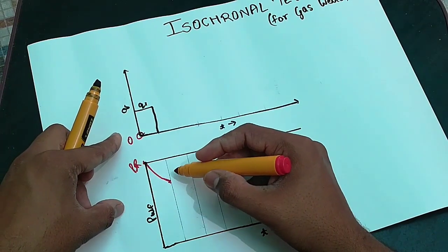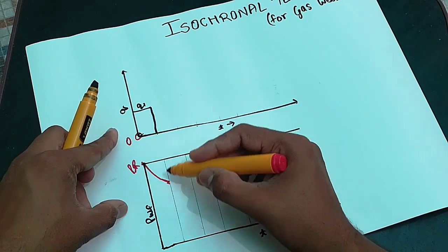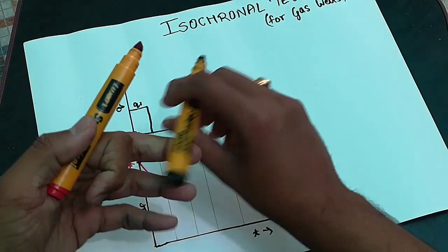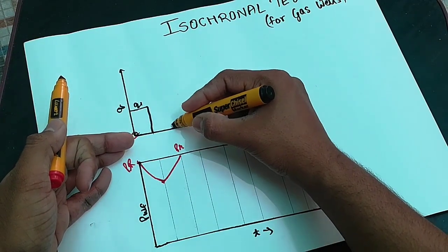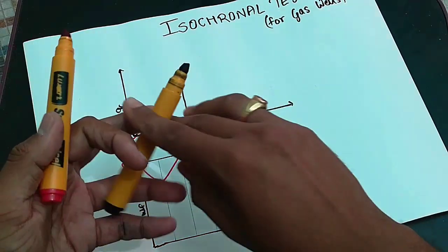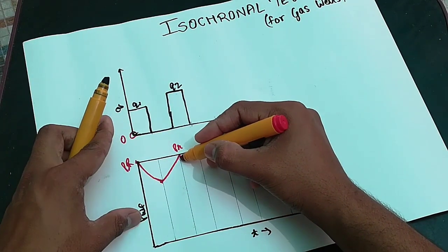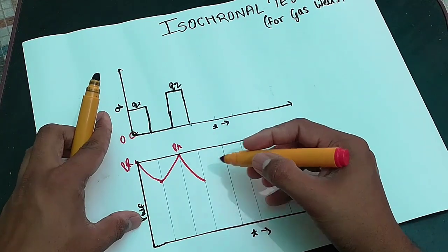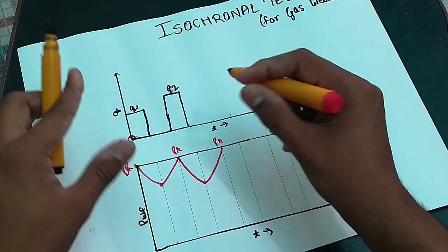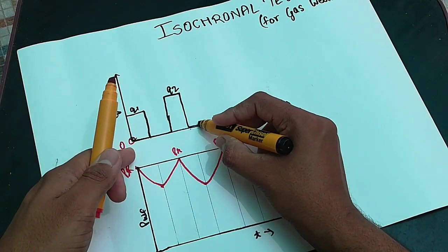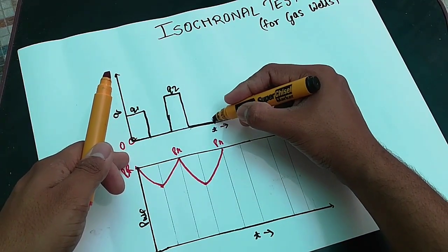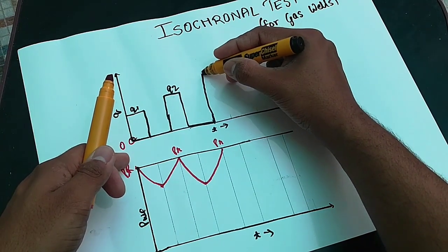Once this pressure drawdown has happened, we will shut in the well for some time in order to bring the pressure back to the PR value. Once this value is achieved, we will once again flow the well with a new flow rate, consider Q2, by which the pressure drawdown will happen this way. Once again we will have a buildup to bring our pressure back to the PR value in this certain period. Once it has reached PR, we will again let our well flow.